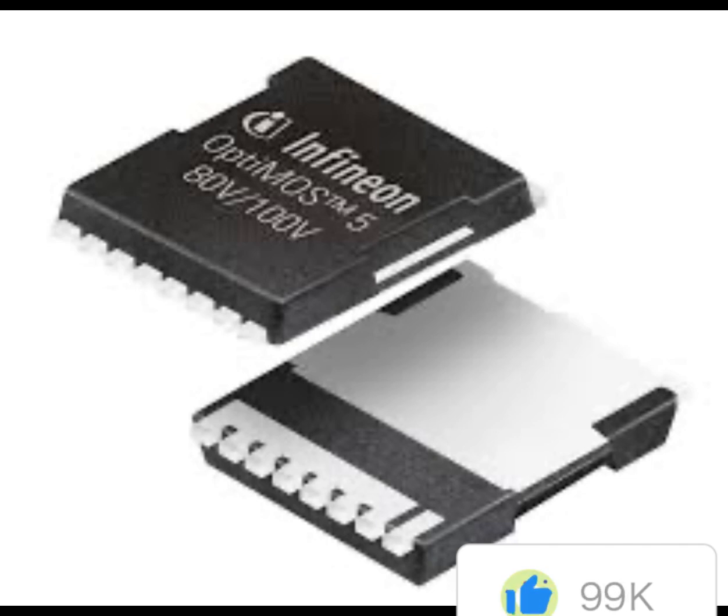Some of the specifications for these SiC MOSFETs are drain source voltage of 1200 volts, continuous drain current of 81 to 113 amps, body diode drain current of 97 amps, pulse drain current of 250 amps, power dissipation of 395 watts, in an operating range and storage temperature of -55 to 175 degrees Celsius.